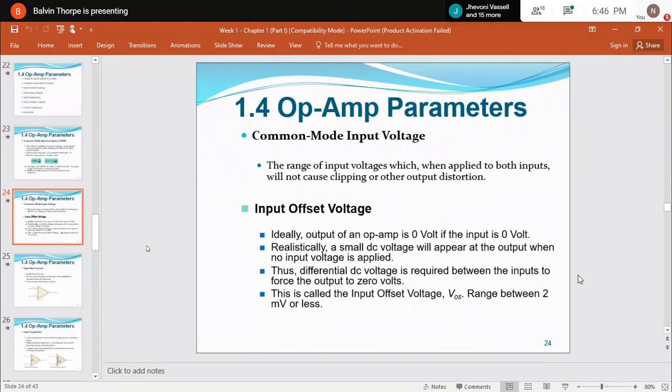Sir, just to clarify, is this an overall term, or do you use it in terms of each input terminal? Like for an op amp, does it have one offset voltage, or one for each of the different inputs? No, remember that you're tweaking both inputs. In that case, you have to tweak the inputs. Or you can put one on ground and then tweak the other one to know what the voltage is going to be that will offset or make the output voltage be 0.